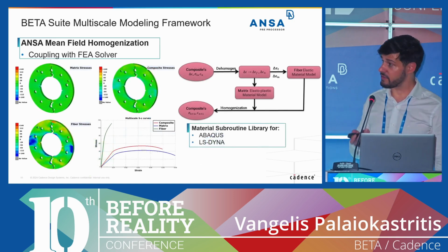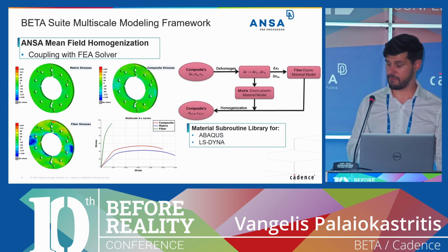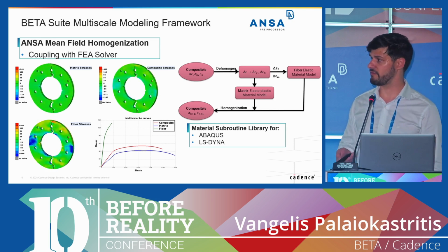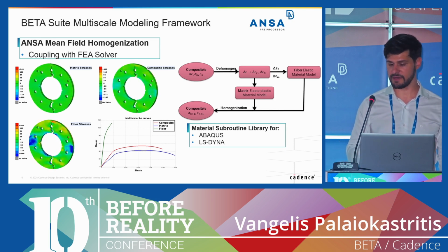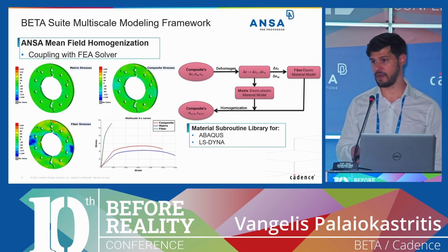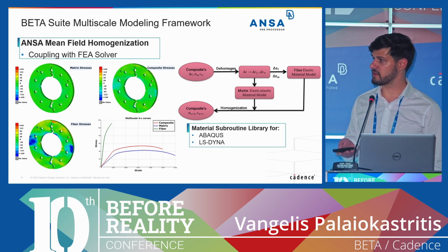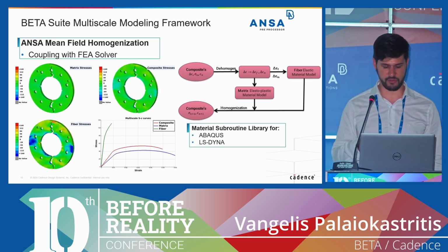And furthermore, an implementation of the mean field homogenization is also available through user material subroutines that are given as material libraries for Abaqus and LS-DYNA solvers.